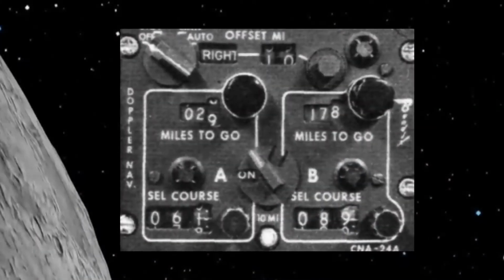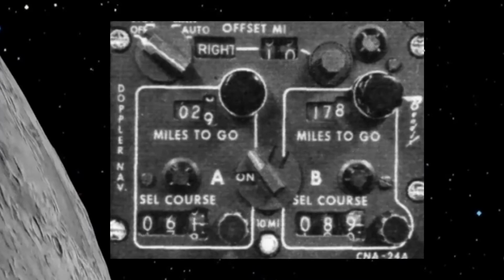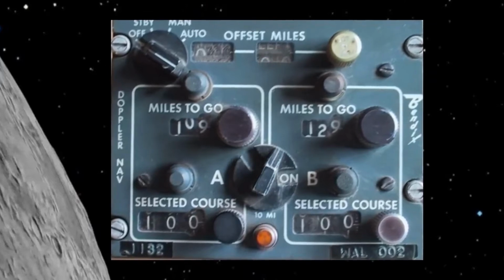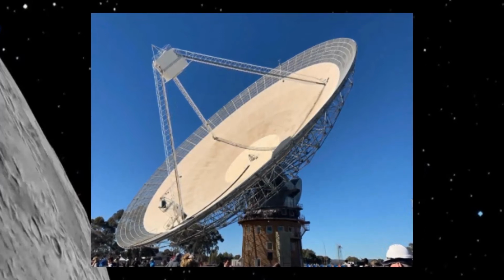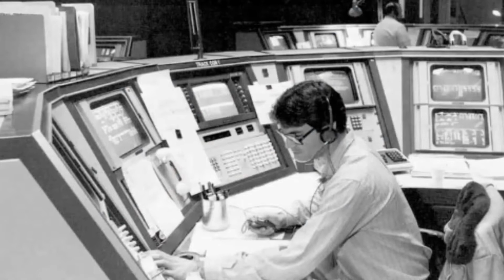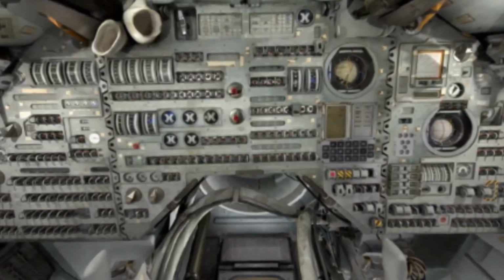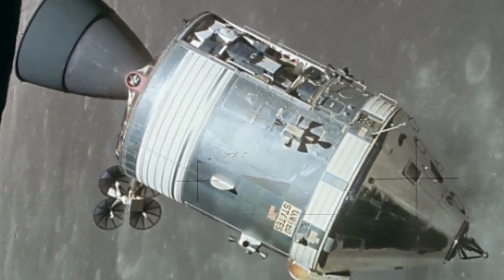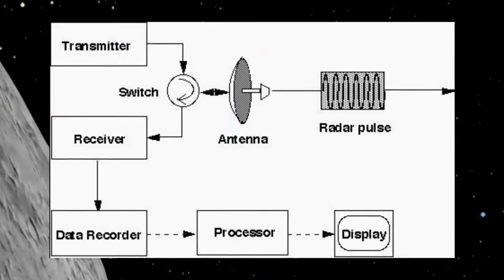However, because of the thermal extremes of space and the excessive equipment needed on board a spacecraft to send signals of sufficient strength using this method, NASA says it found a way to use the Doppler effect without the need for this excessive equipment on the CM. Given that a powerful, accurate radio signal would in any case be sent to the spacecraft to carry voice and data from Mission Control, engineers simply arranged that it be modified on board in a known way and retransmitted back to the ground, this time carrying voice and data from the spacecraft. If the frequency of the signal from Earth was precisely known, then so was the spacecraft's, if it were not moving. After equipment on the ground received the downlink from the spacecraft, the precise frequency was compared to the uplink.